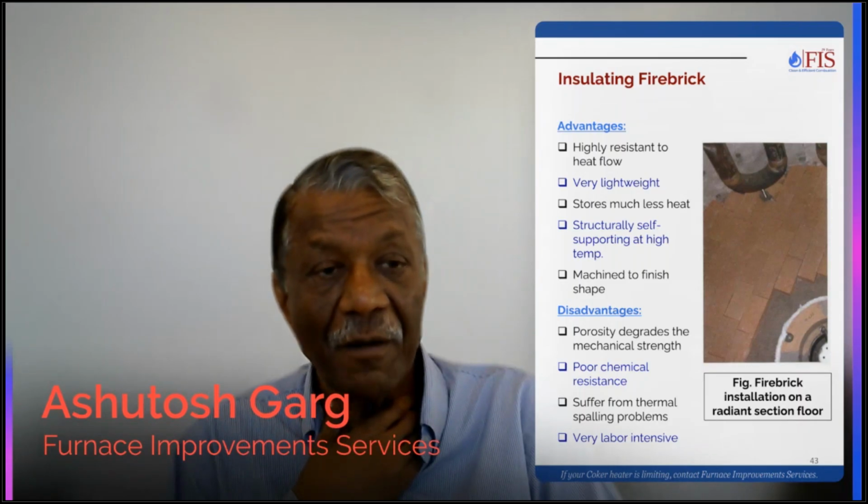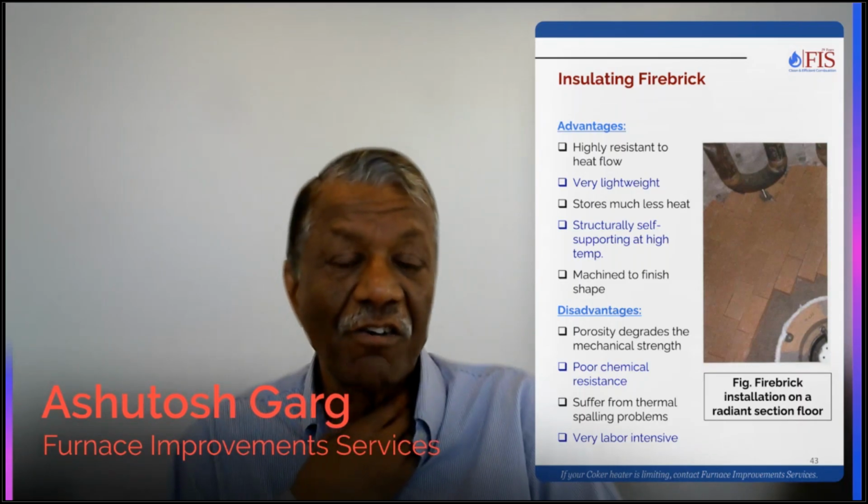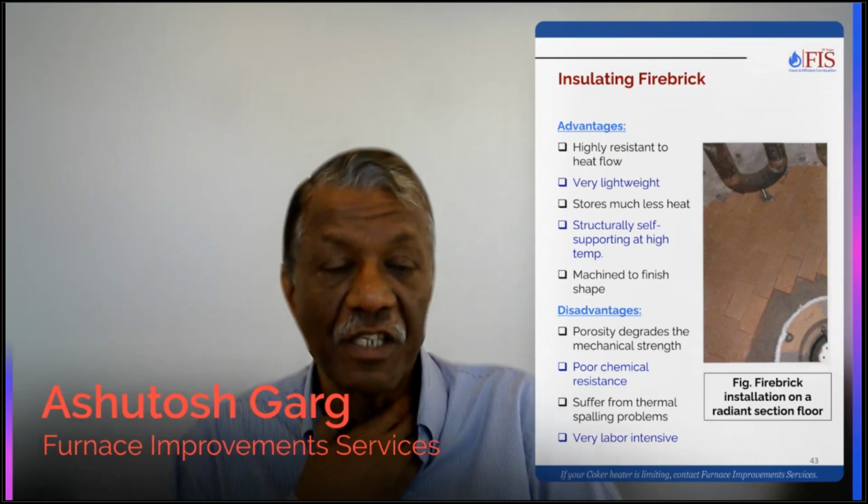This one is showing the fire brick lining on the floor. Even this has been replaced by API, and they allow us to use 2500 degree F castable instead of the brick. So we don't use it anymore. But these bricks were used only for maintenance purposes or for people to walk on the floor. They had no other function.